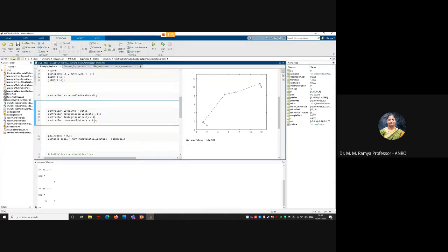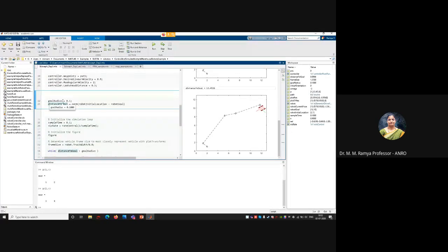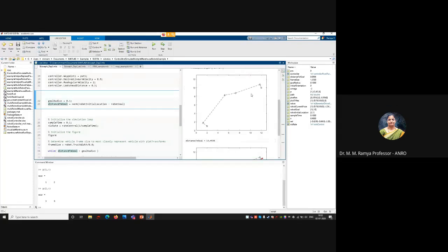You can define it. So after this class, probably you can even vary these values and see how it makes a difference in the robot's movement. Right. Now, I want to know the goal radius, which means this is my goal, right? So the robot keeps moving. If I set a huge goal radius, saying that if it reaches this huge circle, then I understand that it has reached closer to the goal, that is enough. In that case, I will increase the goal radius.